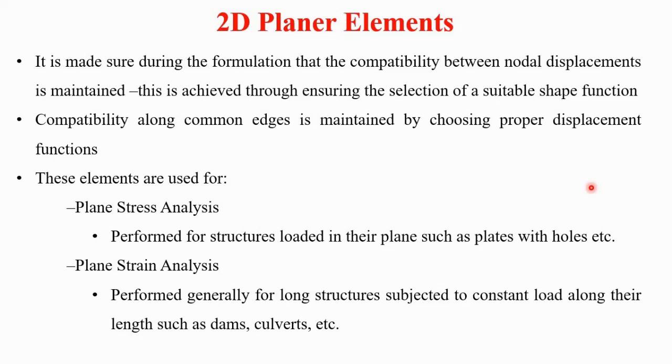Plane strain analysis is performed generally for long structures subjected to constant load along their length, such as dams and culverts. In the case of a dam, the length is larger compared to the width and height, and there is constant loading on the dam. Such cases can be assumed for plane strain analysis.